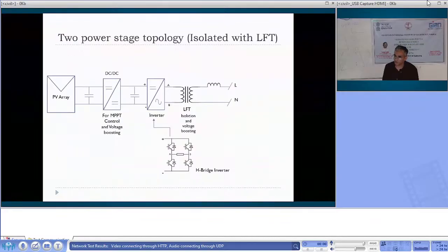Can we have a square waveform? I think Chinese inverters, sorry to say, if you observe the waveform across them, it is a square or triangular waveform. One inverter that Professor Chaudhary gave me had just a triangular waveform, but normal appliances can work on that. The tube light was working nicely, but it kept producing some humming sound. With a simple inverter you can produce a square wave and some appliances may work. Heating appliances, of course, will work. Square waveform means more harmonics.